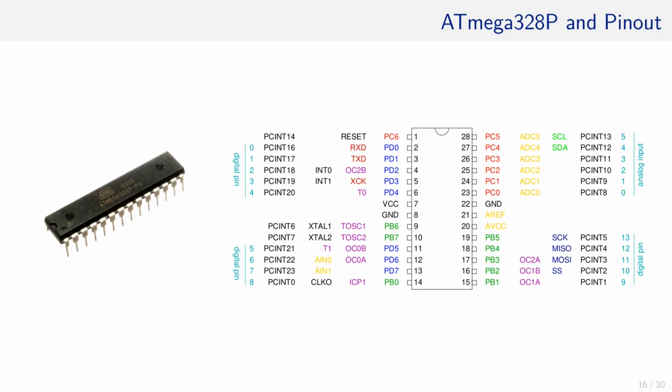In the previous session we saw that protocols can mimic other protocols. As we know, the ATmega328P does not have a one-wire interface. Therefore, its UART can be used for the one-wire purpose. Another observation is that the ATmega328P, despite its small size, has 28 pins, and especially dedicated pins for communication.